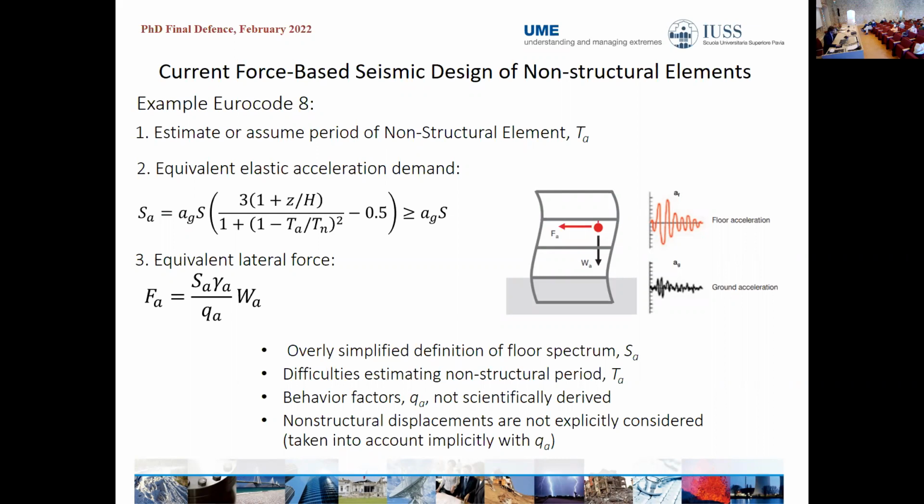So what are the problems with this procedure? Well, first, it has an overly simplified definition of the estimation of the acceleration demand on the non-structural element. There are difficulties in estimating the non-structural period. Behavior factors are not scientifically derived. And finally, non-structural displacements which cause damage to the non-structural element are not considered explicitly in the design procedure, but are taken into account only implicitly through the behavior factor.